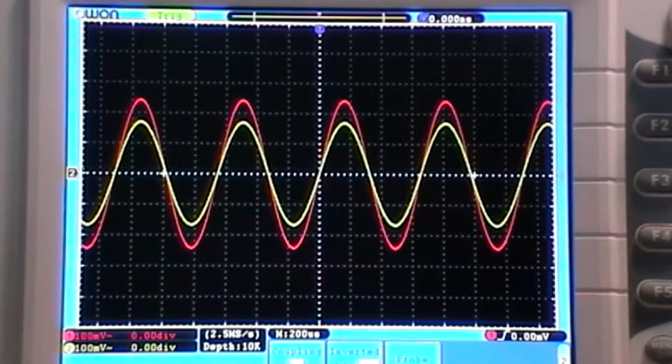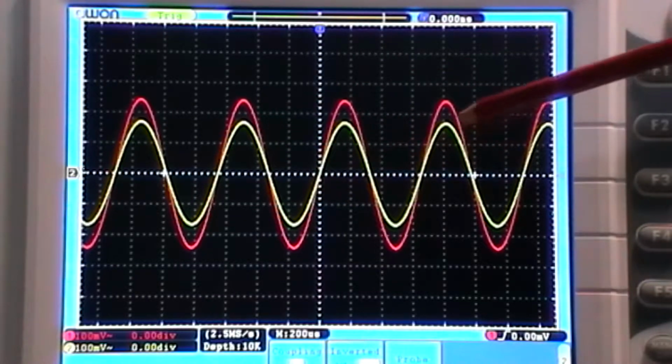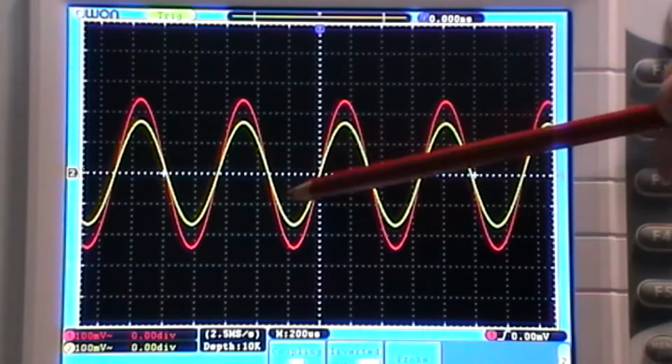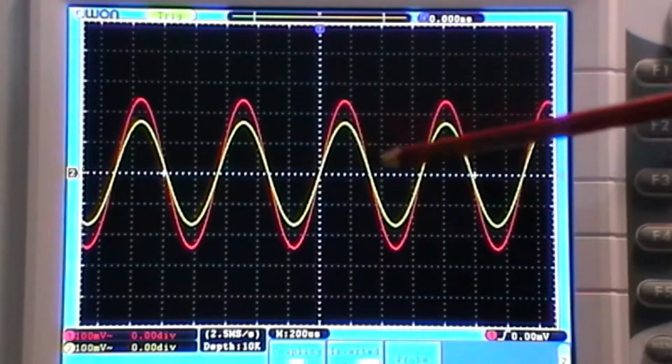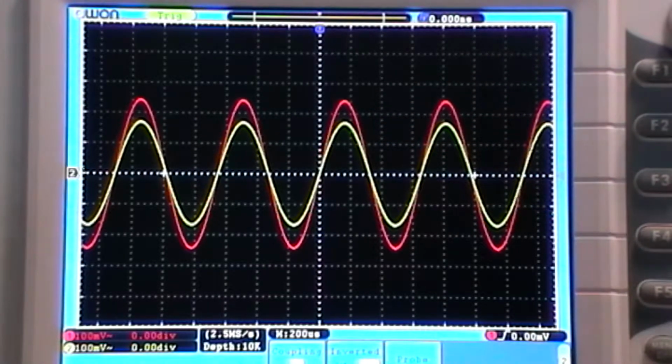And yeah, that's to me a good demonstration that a high pass then low pass filter is a bandpass filter, a passive RC. If you set the high pass filter to have its frequency cut-off point lower than the low pass filter, all the low stuff gets cut off. At the midpoint there's no phase shift, and then as it goes up there's more phase shift towards the low pass, and then all the high stuff gets cut out. To me, I think that works just fine.